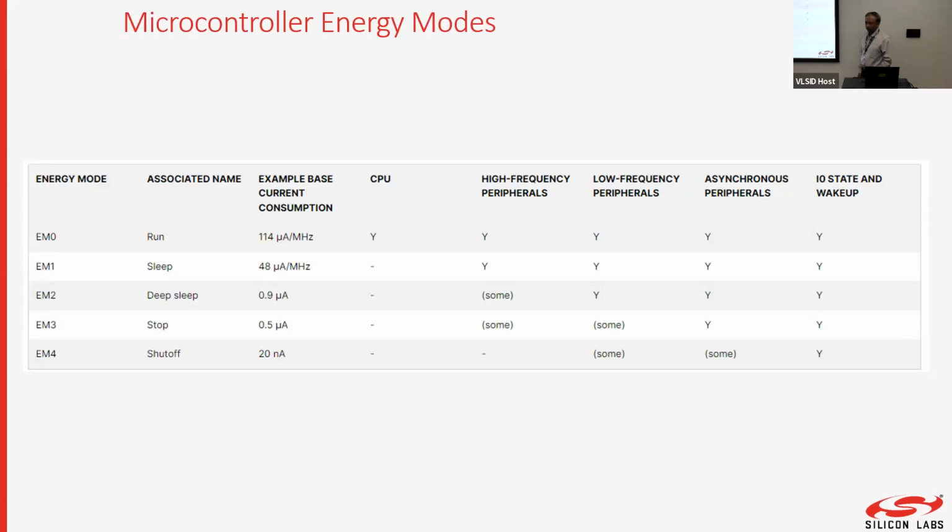If you are just waiting for 3 seconds, you can be in a deep sleep state where you're running a low frequency clock. If you might want to be interrupted by a sensor sending you sudden important information, like somebody opening the door, then whatever is needed to keep that interrupt alive, you enable, and the rest you can turn off.